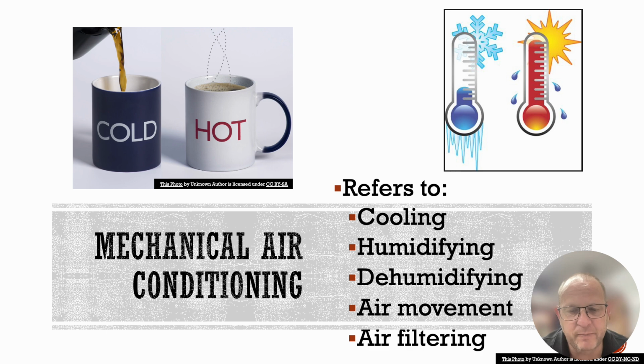Air filtration is important too. With a lot of individuals having allergies, we want to make sure that we're filtering the air very well. Not so much done well on mini splits, but on a whole house air conditioner, we can put some really good filters on those units with the ability to catch many particles of viruses, bacteria, pollen, and dust to help the individuals breathe within that house.